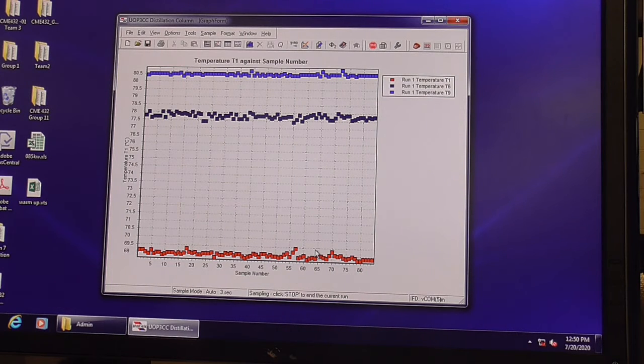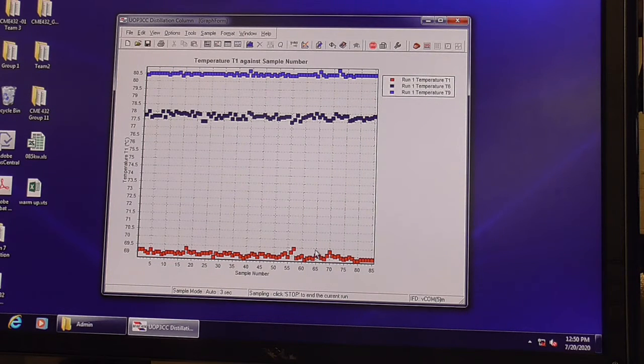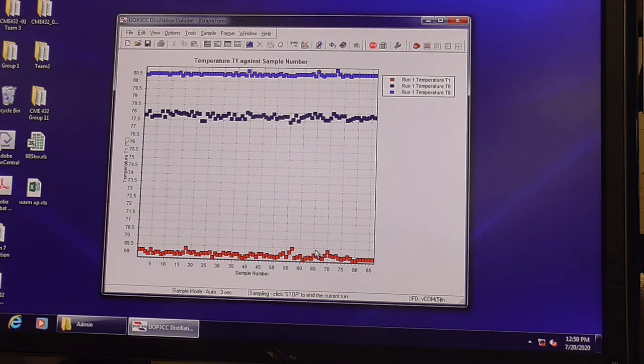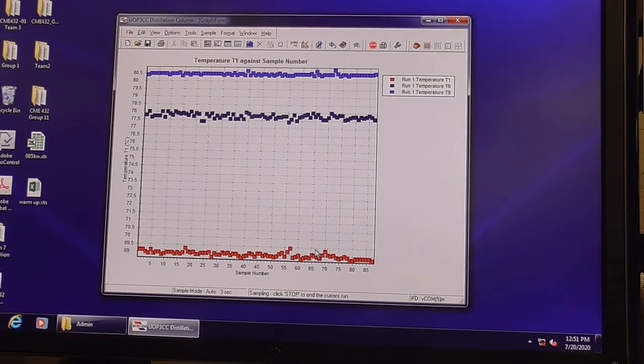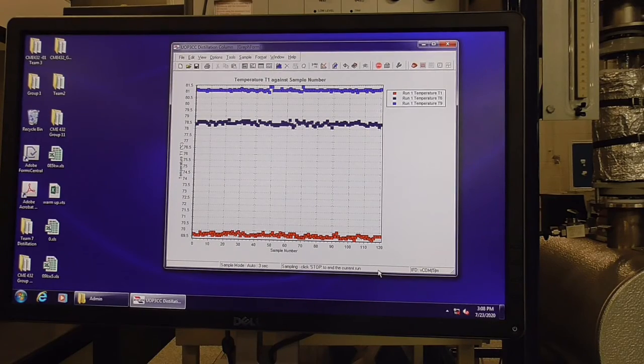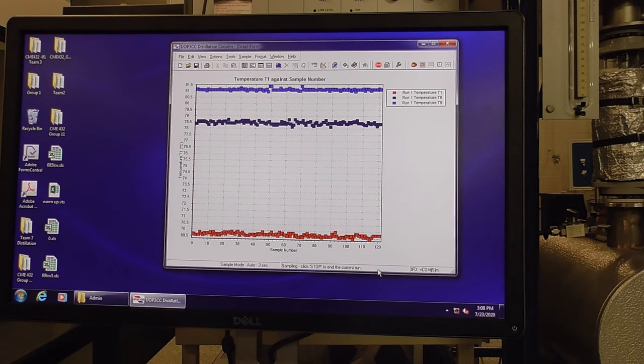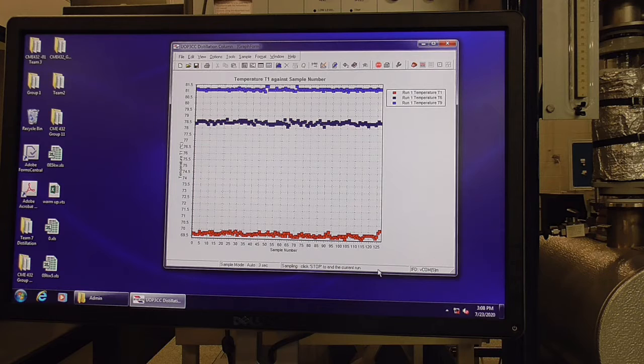Here you see a temperature plot where I've been warming up and running at full reflux for some time, and now I'm ready to turn on the feed pump and the reflux valve. We warm the column up and start running in full reflux with the reflux control valve off. It's in full reflux. All of it refluxes back on the column. When you've reached the steady state temperature like shown here, you're ready to start feeding and turning on the reflux and getting back to your second thermal steady state.